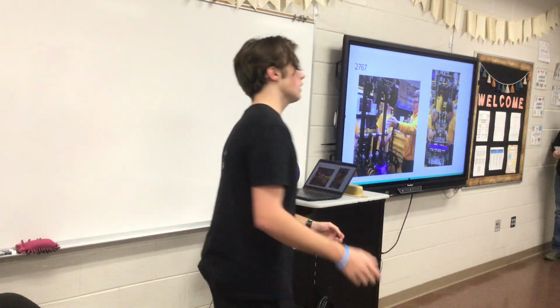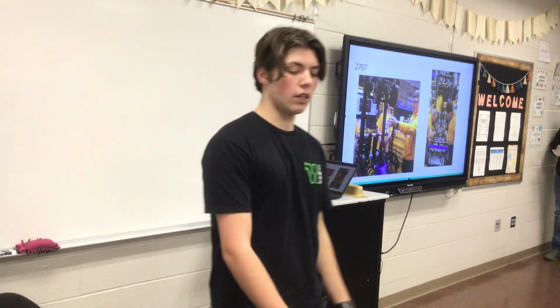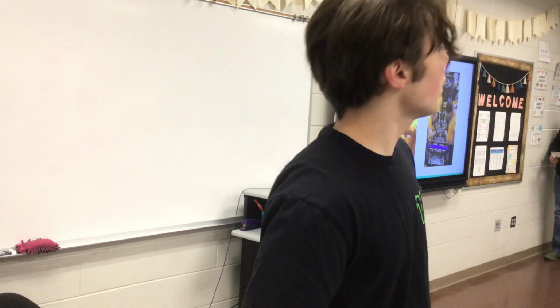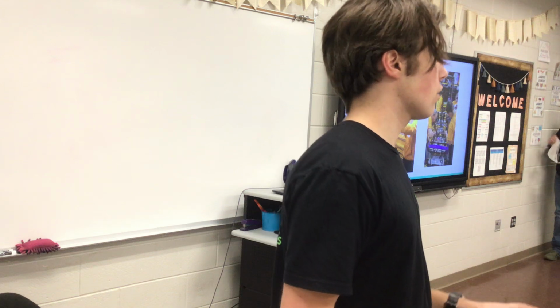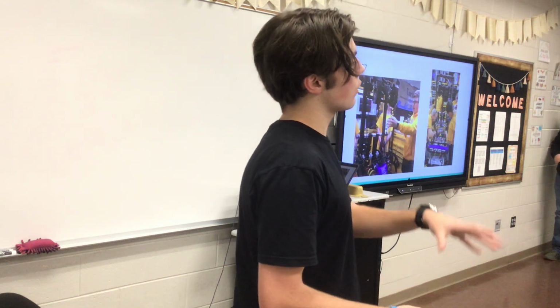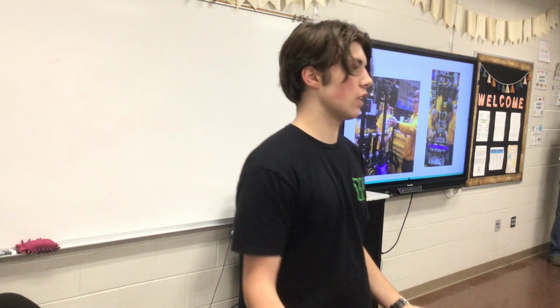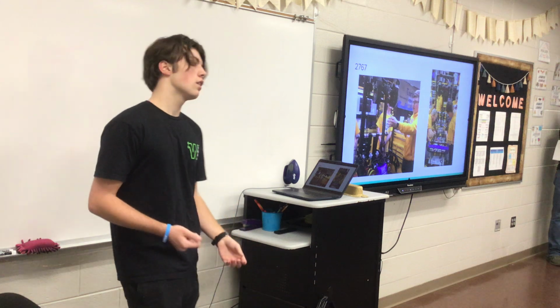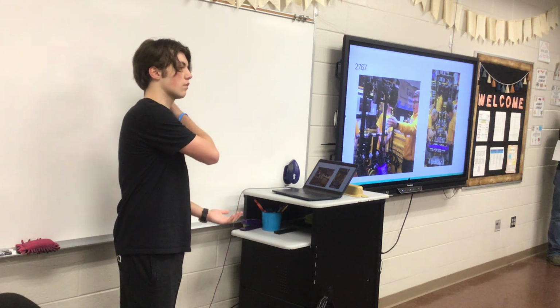Depending on your experience, we hosted a workshop where we made, I think, 4 panels like this in a lab, to get some experience working for ourselves. It took about 4 hours to get everything set up and start the curing, and then we cured overnight to get the pieces. So if you're interested in time, that's how long it took for us. But we also have a mentor who is very experienced with composites.